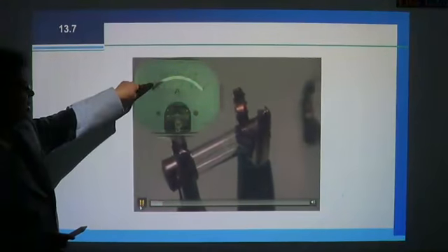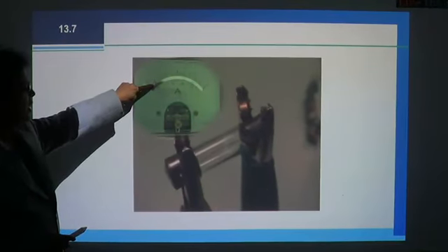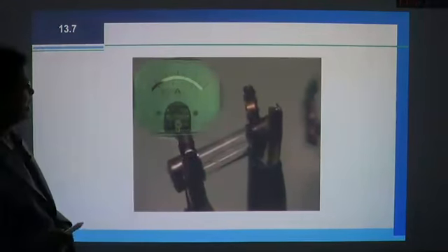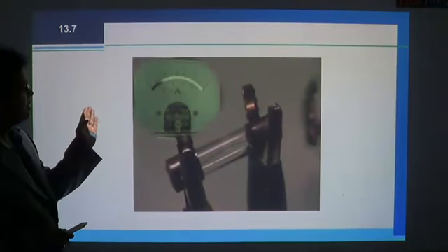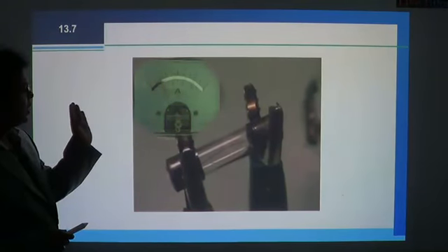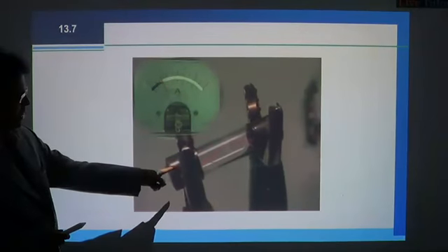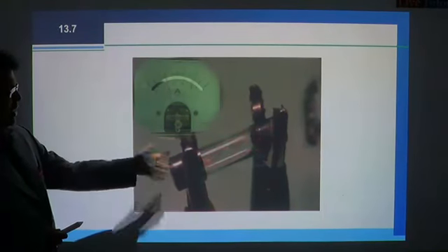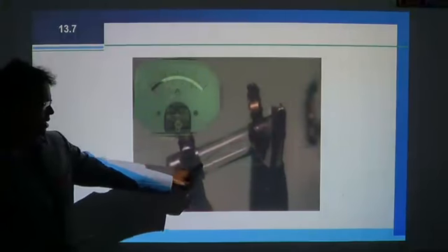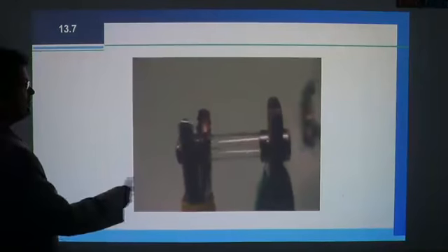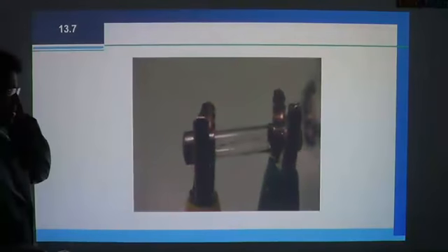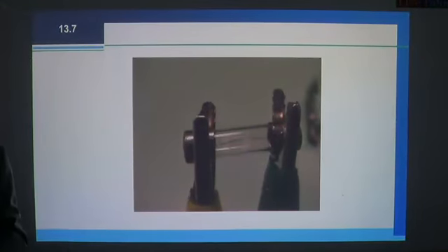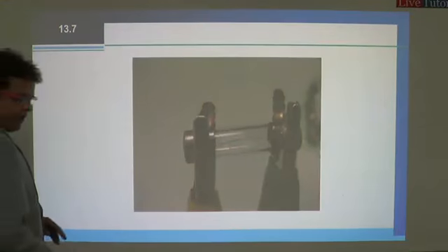Now the current is here. Slowly it is going to increase now. When it is increasing, look at that wire inside, the fuse wire inside. What is going to happen? Now it is slowly increasing from 0 to 2 ampere. Now you can see that it is becoming red hot. After that it reaches the maximum heat, maximum current, so that it cannot withstand that current, so it gets cut. The circuit is broken now. So no current will flow through that. So this is how the fuse wire is working. A very simple application of Joule's law of heating.